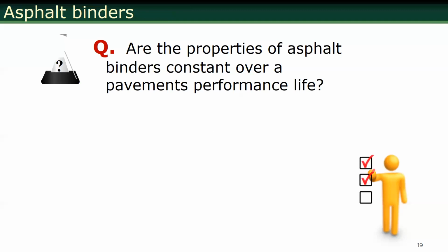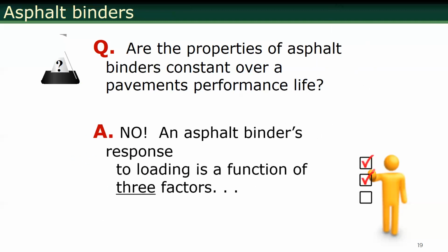Those are extremely important because we are simplifying a nonlinear viscoelastic material into a simple case. So the point I'm trying to make is asphalt binder is complicated. We have to follow the specification very carefully to test it. Now, asphalt binder's properties do change with time.